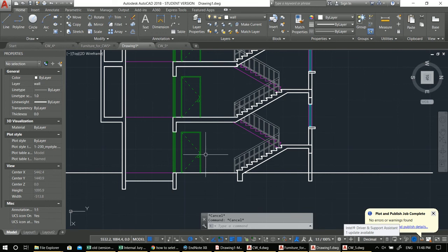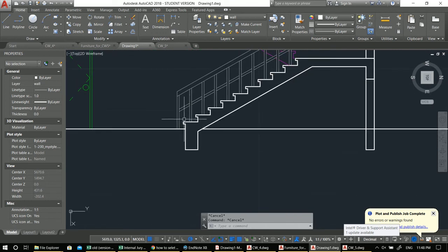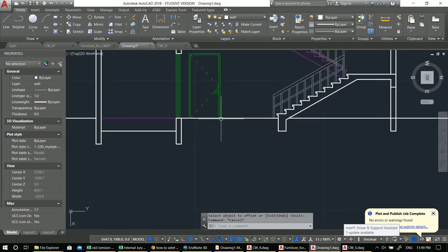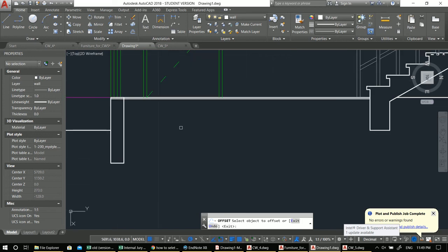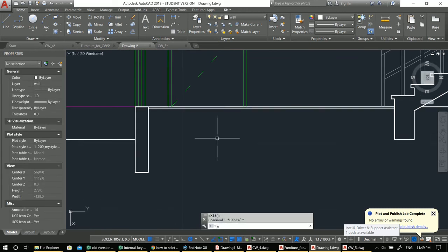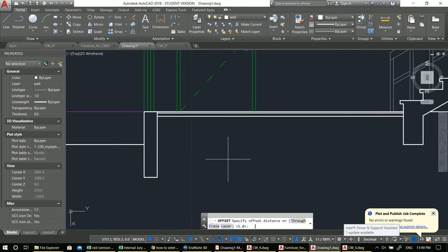Here for the stair, you can do a more detailed drawing of the first step, and then you can have your layers of the foundation and everything. So offset, I don't know, 2 centimeters, like somehow finishing here, and then under it you will have 5 centimeters of concrete, and then under it the base stonework for slope adjustment and those kinds of things.